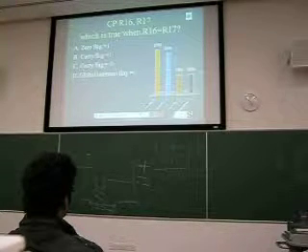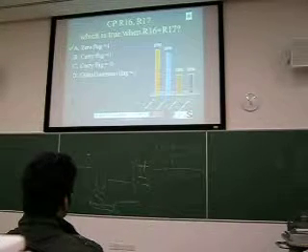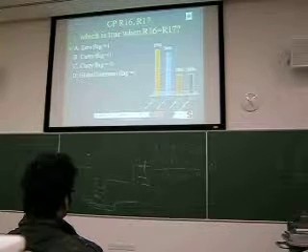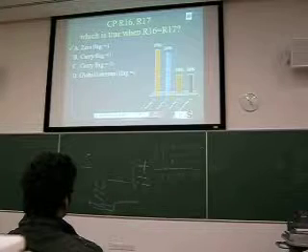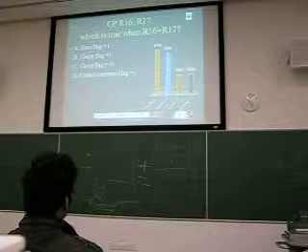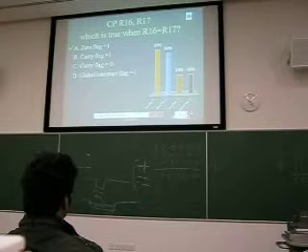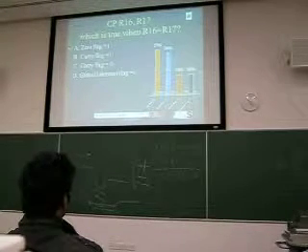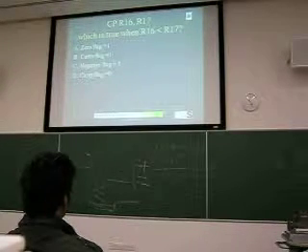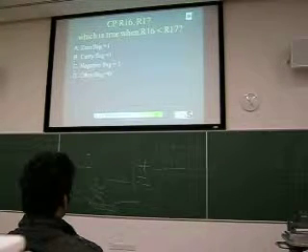Okay, let's see. Let's say I didn't know the answer, and I'm doing the lab today. I could look it up in the instruction set manual. It will tell me which flag is going to be set. Okay. So when they're equal, the zero flag is set. But now let's say they are not equal. So for example, in my next one, let's say this value is less than this one. Which of those flags